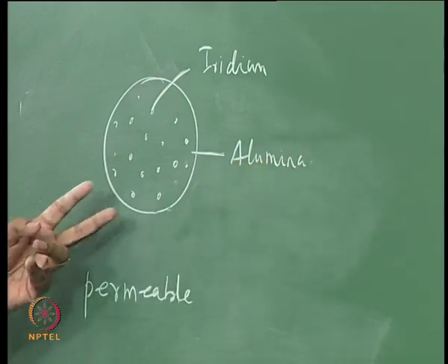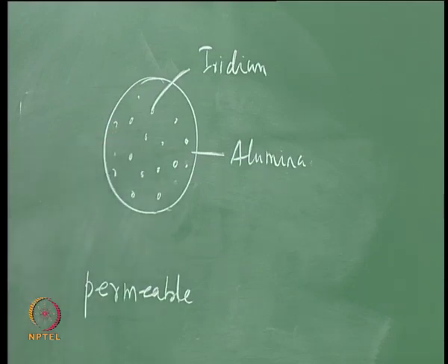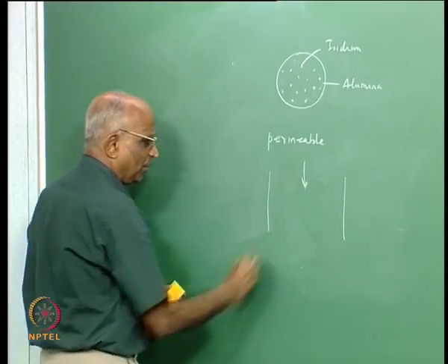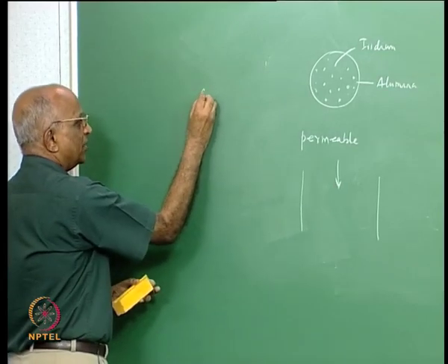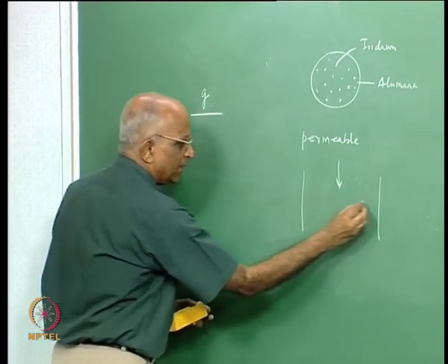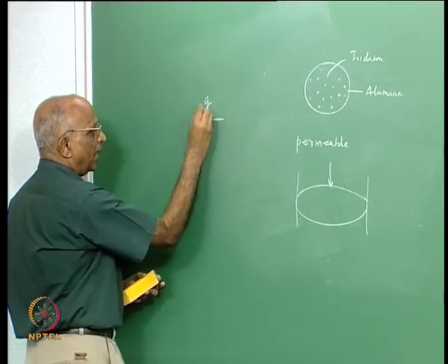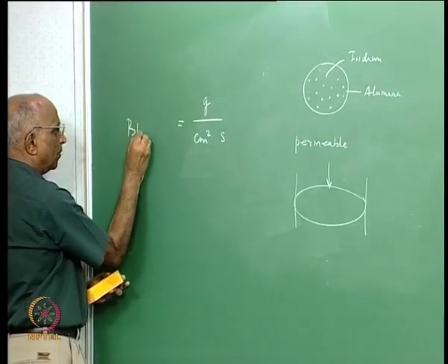It must be permeable, and therefore how do you design a catalyst bed? After all, you have a bed of a certain size and hydrazine flows into it. Therefore, it is specified in terms of mass flow of hydrazine in grams divided by the surface area, that means so much per centimeter square, and you are flowing per second, and this is known as bed loading.